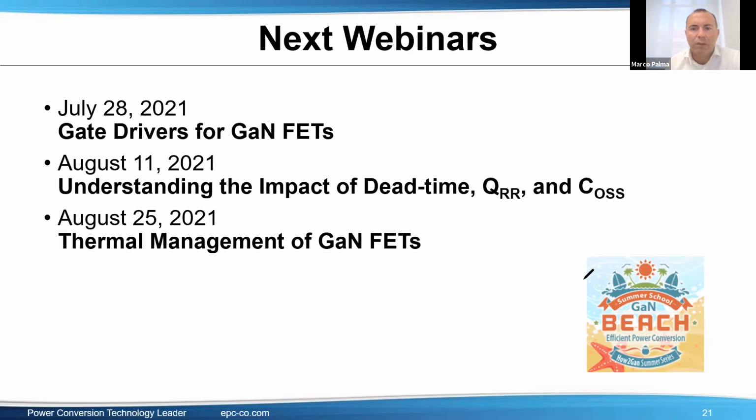The only drop-in replacement of a MOSFET is a cheaper MOSFET. GaN FET is going in a completely different direction, is changing the system, is improving the system properties. So if you take a MOSFET inverter or converter and just remove a MOSFET and put a GaN FET, you have only two chances. Either it works in the same way the MOSFET inverters were working, if you're lucky, or it will work even worse. So it's not really the way to do it.